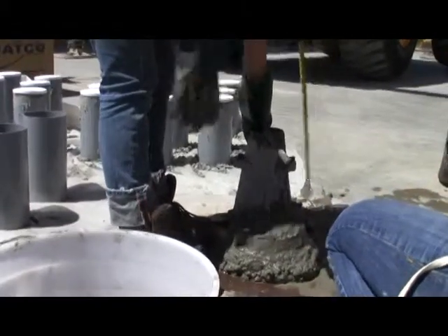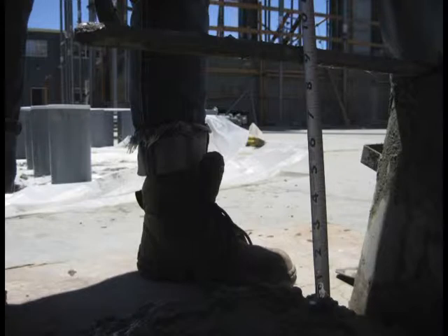After the slump settles, the metal rod is leveled horizontally on top of the cone, and the distance from the horizontal rod to the top of the concrete is measured. The change in height of the concrete sample is referred to as the slump for that specific batch of mix. The slump measurement is compared with specified values, and a decision is made to accept, modify, or reject the concrete mix before placing the concrete.